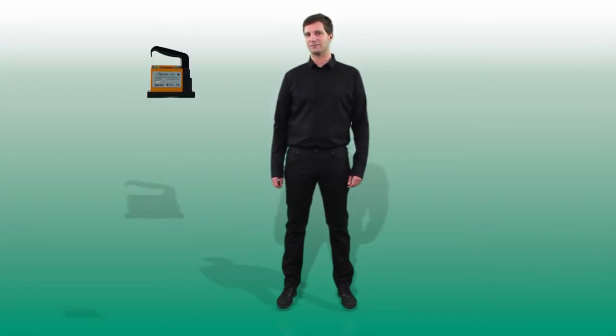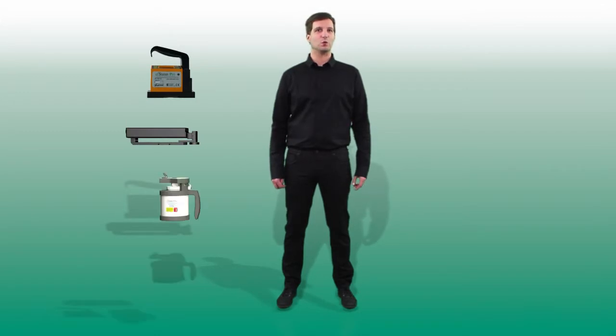The next issue we want to address is that of accuracy. What accuracy are we looking for, actually? In mechanical engineering applications, we normally are looking for something between tenths of millimeters to micrometers. The following instruments are frequently used for the measurement of flatness: precision spirit levels, interferometers, and precision sweep lasers. However, surprise, surprise, each instrument and method has its advantages and disadvantages.